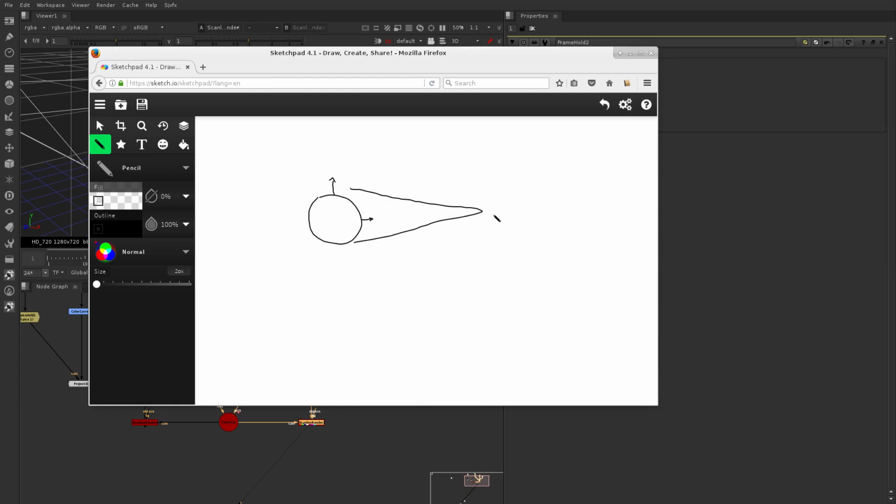Okay, let's say we don't have a camera, but we have a light instead. And so we place a light here, and we assign a diffuse shader. What the diffuse shader will do is basically use the Lambertian law and give us, based on the surface normal and the light, either 1 or 0, and it's going to blend between them. So the light that hits this point will give us back 1, and the light that hits this point will give us back 0, and anything in between.